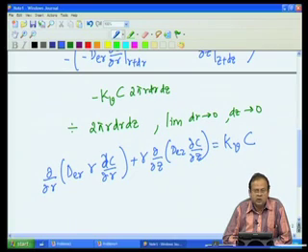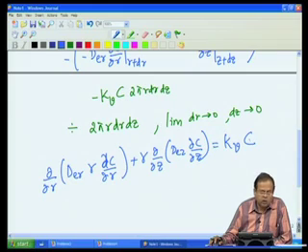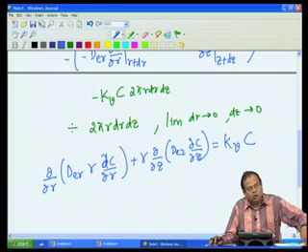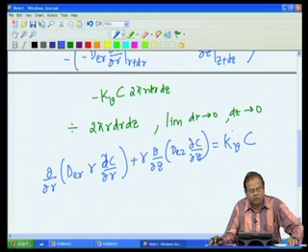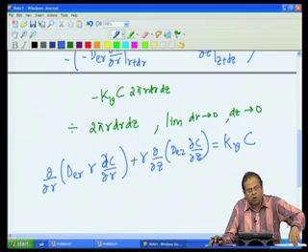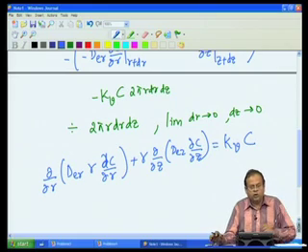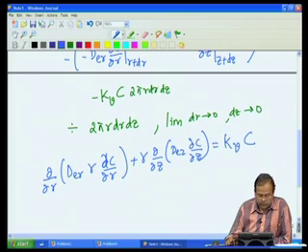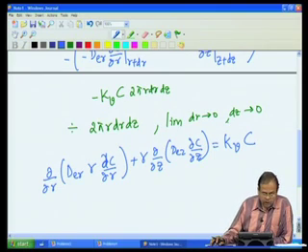If an energy balance is involved, we can write a similar balance, except heat of energy will come and ∂T/∂r, ∂T/∂z terms will come. What kind of equation is this? It is a partial differential equation, and what is the order? Order is 2. So, we need two boundary conditions in two variables r and z. So, let us try to write down these boundary conditions.